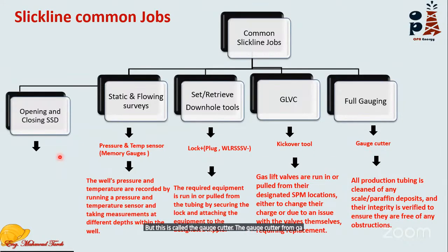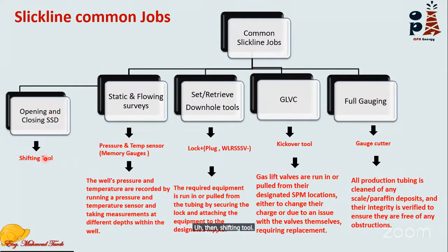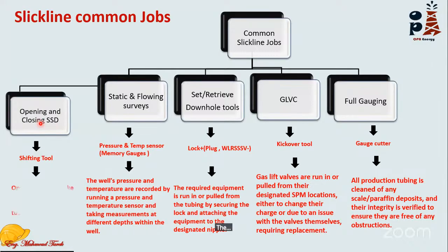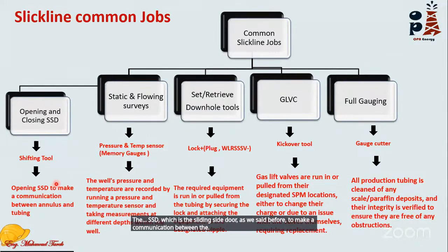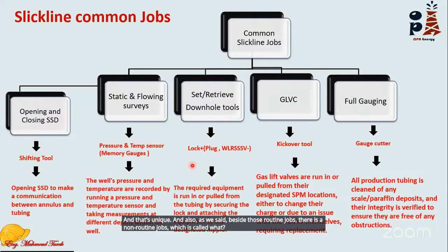Okay, the shifting tool is attached to our PHA as the main tool. This main tool is attached to our PHA regarding what? Regarding opening and closing the SSD, which is the sliding side door, as we said before, to make communication between the annulus and the tubing. And also, as we said, beside those routine jobs, there are non-routine jobs, which is called what? Which is called a fishing job.